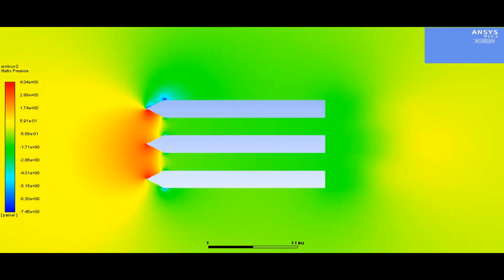Next, we can see our pressure contour. As the video shows, there is a high pressure area where the water contacts the front of the pontoons and low pressure pockets on the outside of the pontoons. These low pressure areas exist because the water is contacting the pontoons at a slight angle and not directly along the x-axis. The pressure around the pontoons is constant because there is nothing for the water to push against. Overall, this is the expected result from the pressure contour.